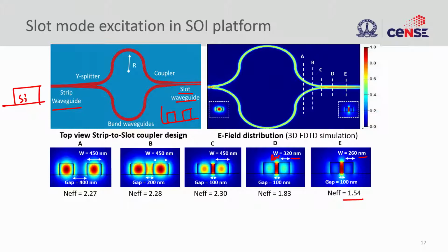So this might be a little bit confusing, right, coming from our waveguide understanding. So when you have higher refractive index, light will be confined inside the core. So this structure is very different, right, where you have two high refractive index regions separated by a low refractive index medium. So you are squeezing the light, right, in order to push the light outside. So what we mean by that is you have two rails, right. So two solid waveguides that are in cutoff, right,